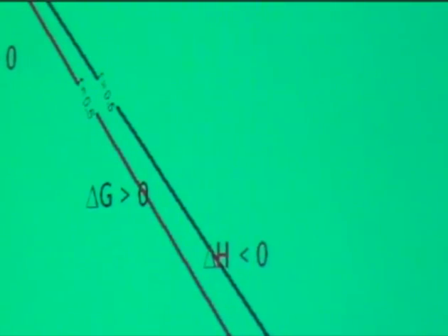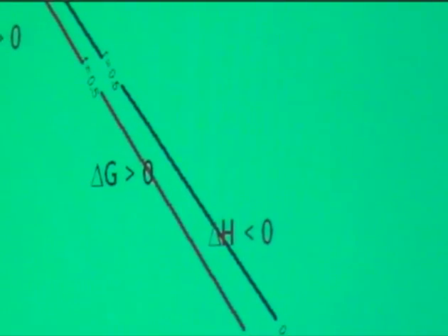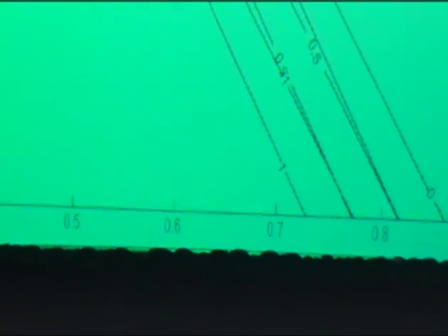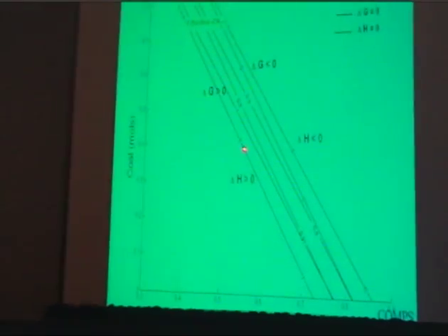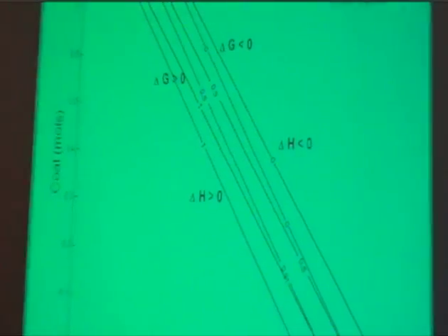Likewise, we can similarly show delta G on the two sides of the curves. Below the curve, delta G is greater than 0, which means we need to put work in, and on this side we can extract work from our process. And again, these are plotted on coal versus methane. Apologies, we just can't see the methane curve at the bottom here. So if we zoom in, what we've plotted here are the extreme cases. In this case, 1 is a pure FT process, and in the 0 case, we're looking at a pure methanol process, and we've shown the half process in the middle.